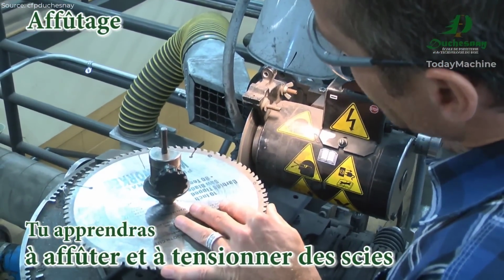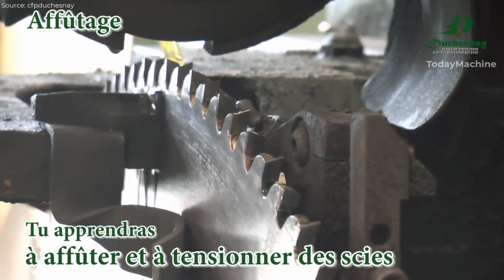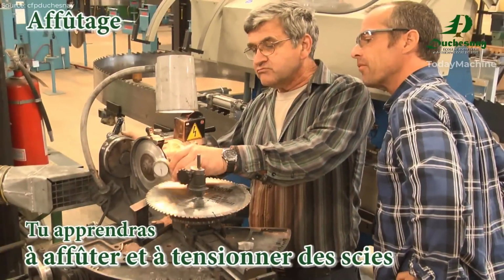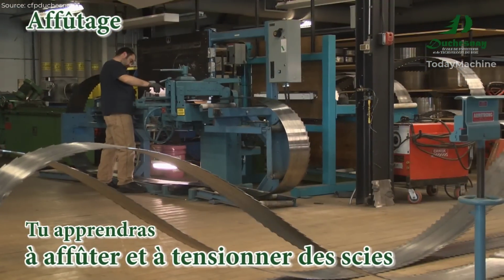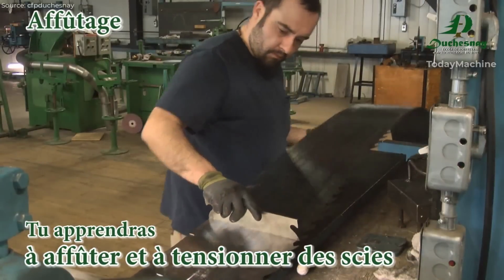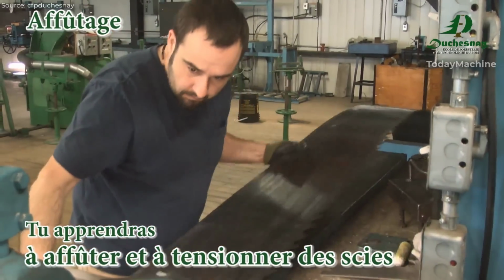Detecting and correcting anomalies. An essential part of your training will be learning to identify and correct anomalies in saws and knives. This could include detecting irregularities in the blade surface, such as cracks, nicks, or warping, and knowing how to address these issues to prevent accidents and ensure the tool's longevity.